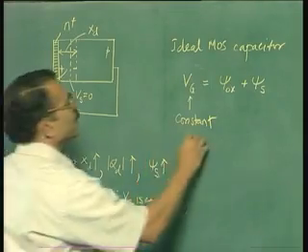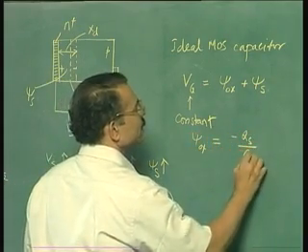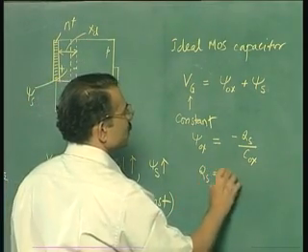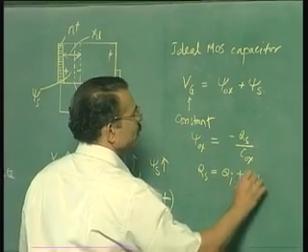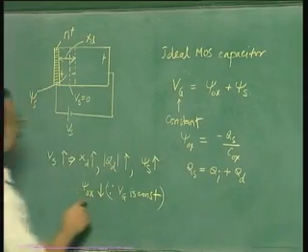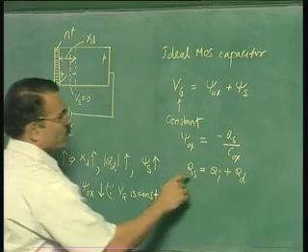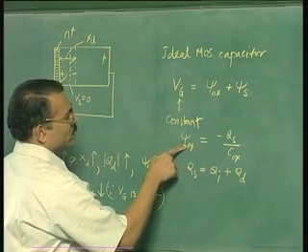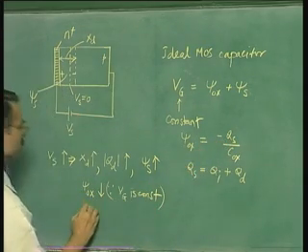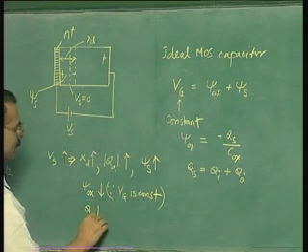So when you write psi ox is equal to minus Qs by Cox, and Qs is Qi plus Qd, that is inversion charge plus depletion charge, then what follows from this condition is that Qs falls. If psi ox is reduced, then it obviously means Qs is reduced. So another effect of Vs is Qs falling.